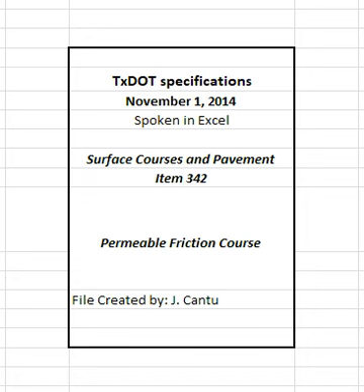The contractor may submit a new mixture design at any time during the project. The engineer will verify and approve all mixture designs, JMF1, before the contractor can begin production. Provide the engineer with a mixture design report using the department-provided template. Include the following items in the report: the combined aggregate gradation, source, specific gravity, and percent of each material used.